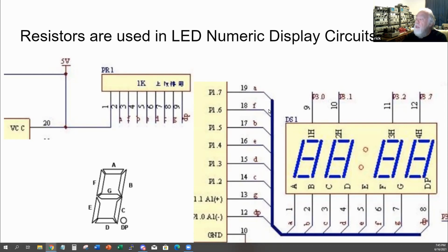And so a bus on a circuit diagram is normally indicated by taking a collection of signal wires that perform a similar function to each other and wrapping them into a wider lead or wire that shows a direction onto the destination of the signals and where they end up. So rather than having to look at 8 or 9 different wires and follow them, you just follow the names of the signal from one end to the other, and you can understand what the circuit is doing logically.